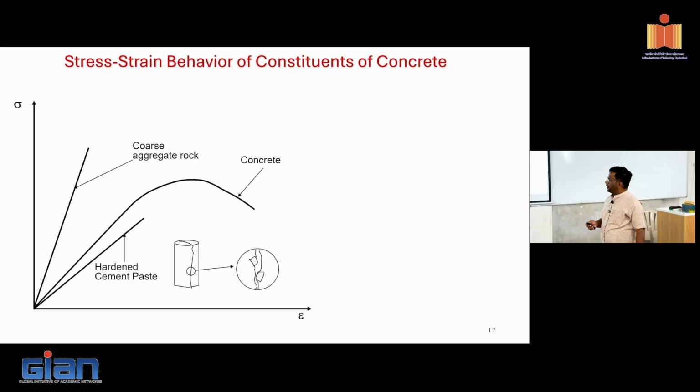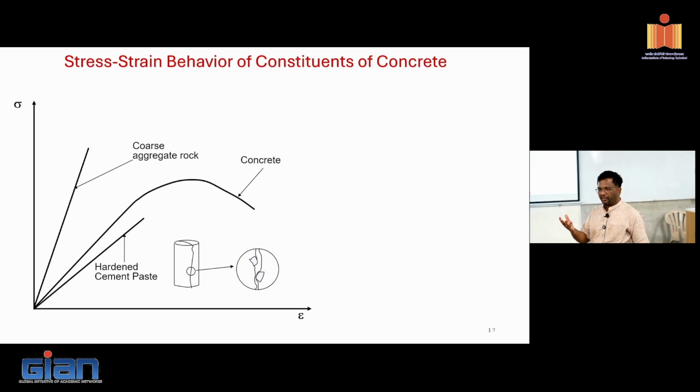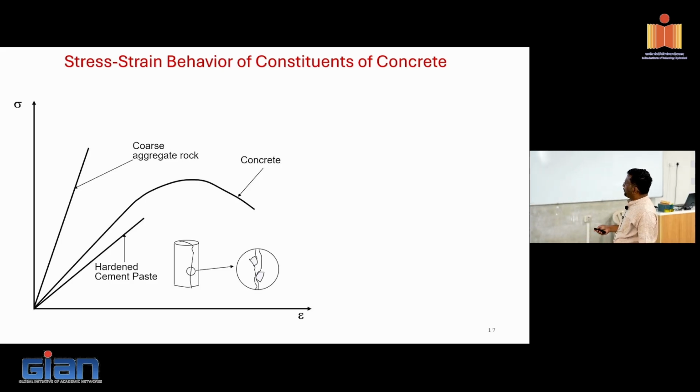Now, in a normal concrete, which is the stiffer material? Let me quickly ask before that: in a typical volume of concrete, which is going to occupy a larger volume? It is aggregate. What would be the rough percentage of proportion? 60 to 70%, it will actually be the coarse aggregate. Then cement: in a typical mix, what is the maximum cement content we use per meter cube? 300, 350, 400; 450 is on the higher side actually. Precast maybe 400, right? It's only 400 kg per meter cube. So you see here, the majority of the composition is from coarse aggregate.